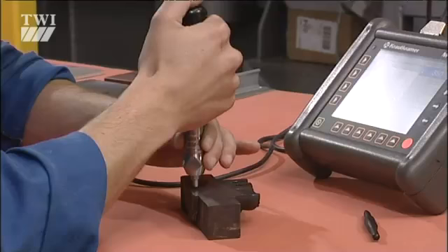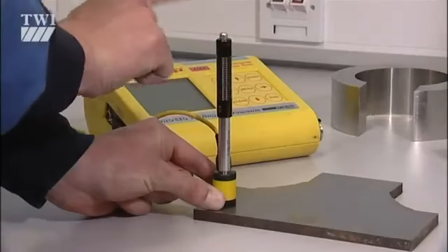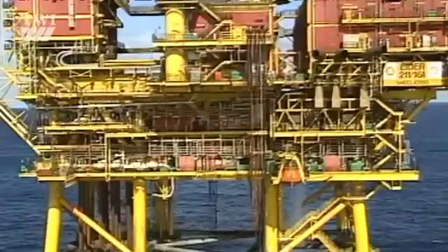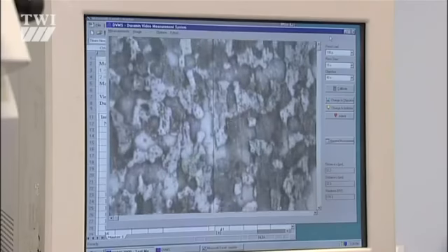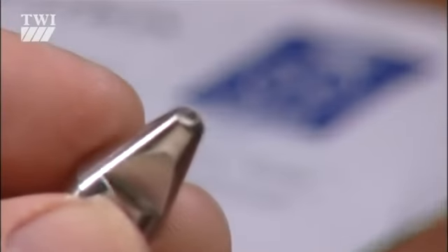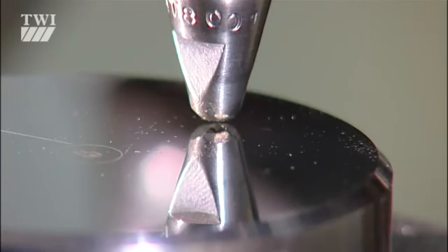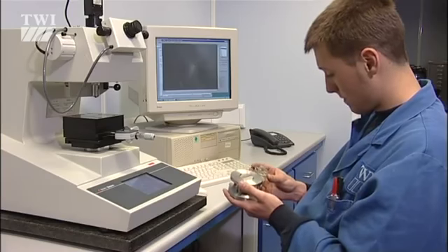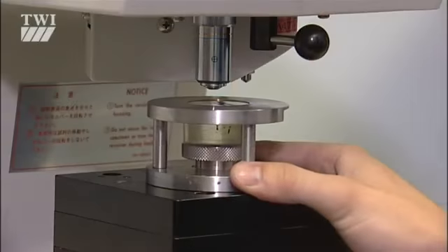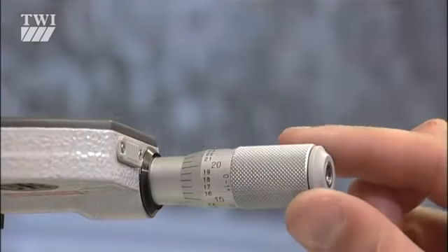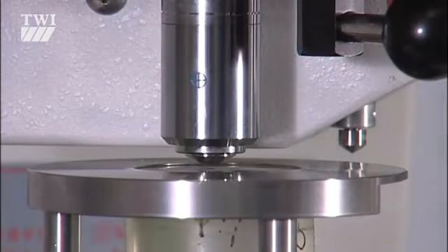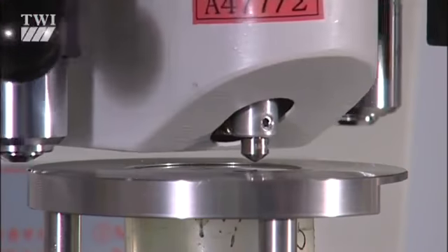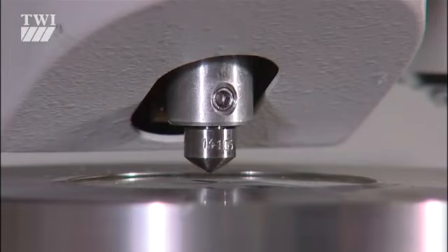Now to specialist hardness testing, for determining hardness in cramped environments, or in-service components too large for the test laboratory, or indeed on very small samples. There are 3 common methods: the Knoop test, the Vickers test, and the micro-hardness test. Both the Knoop test and the Vickers test use a pyramid-shaped indenter. The loads are scaled down appropriately to between a gram and a kilogram, and produce impressions that require 100 times magnification microscope to see and measure.